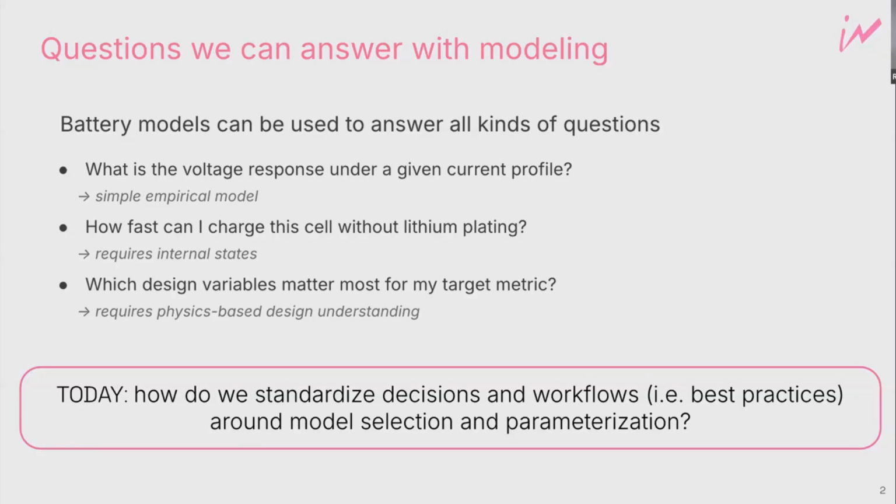Obviously, for those second two questions, you're going to need a very different kind of model, because those questions require you to either have some insight into internal states. If you're looking at lithium plating, you might want to track the anode potential, for example. Or they require you to have some kind of link between design parameters that maybe you care about in manufacturing or cell design. These might be thicknesses, loadings, porosities, etc., and how they link to cell performance.